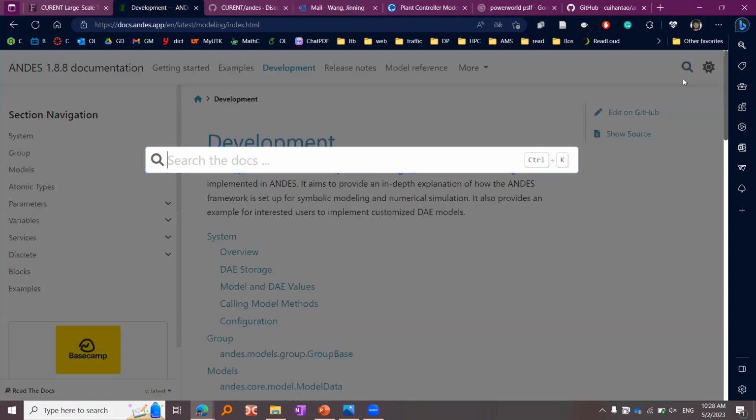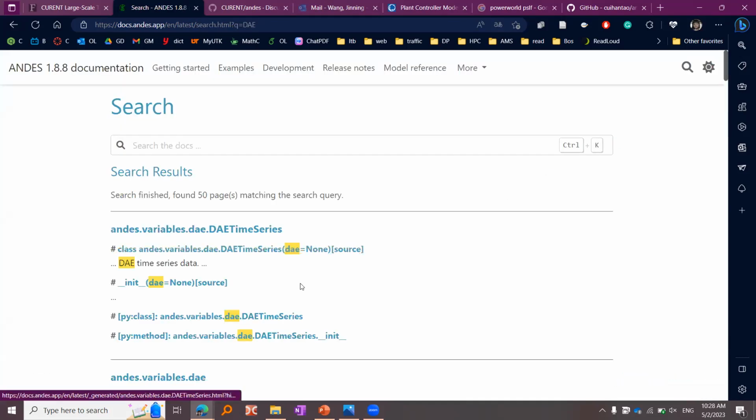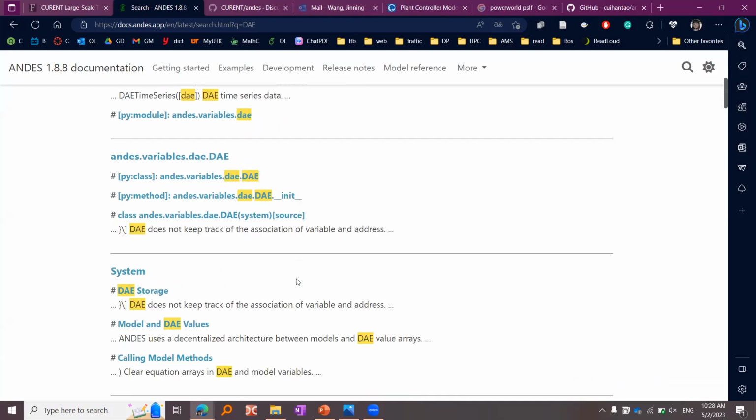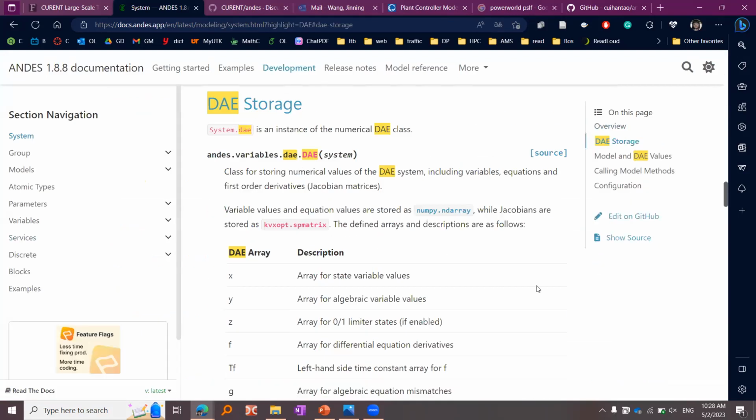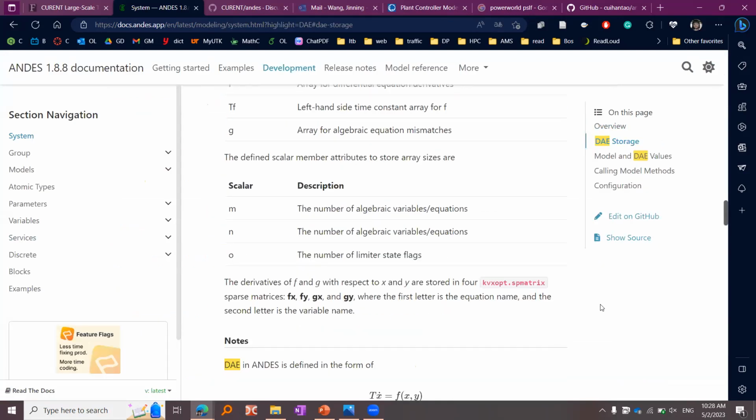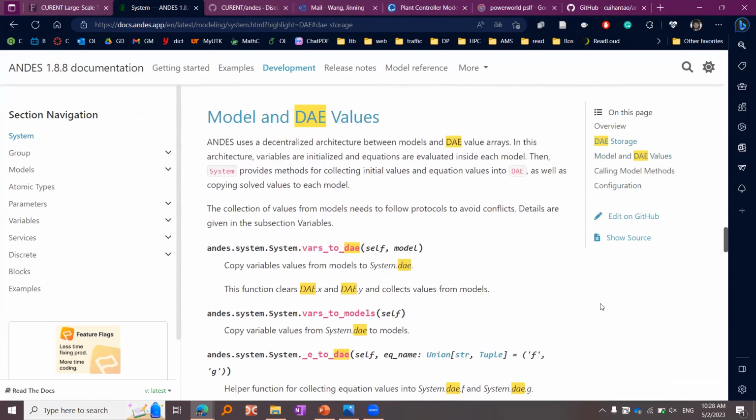So it can do variable time step, which is also needed. When you're doing real time, you don't really do that. But one of the reasons you want variable time step is that when you have a disturbance, you get a shorter time step and your integration is more focused. Then as things die out and aren't changing as much, you can get a longer time step. So you're going to be much faster there, but it's also numerically stable. With implicit integration, I don't know that we've really tested this, but it should be able to run for hours without diverging.